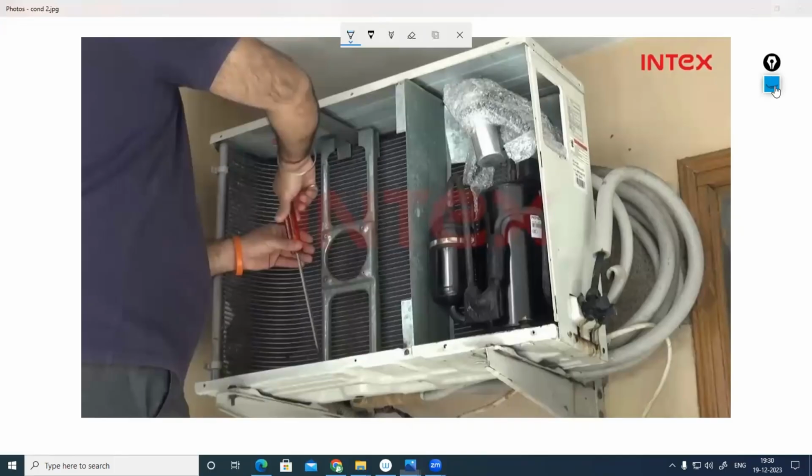this one. And what material are we using here? The material that we are using, this one, no? Copper only, definitely. Can we use any other material? We can use it, no problem. Aluminium we can use, but practically it is not cheap, it is less used, and if there is any damage, the chance of leak will be more. That's why most machines connecting indoor unit and outdoor unit will use which one? Copper only. Copper also, two types of copper pipes are available in the market.